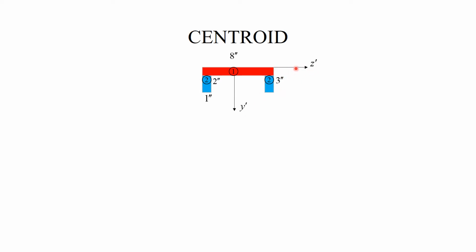Z bar is located at the upper fiber so that all Y coordinates are non-negative. And I emphasize here that because of symmetry, the two webs have the same property, and I will take this into account in my calculations.